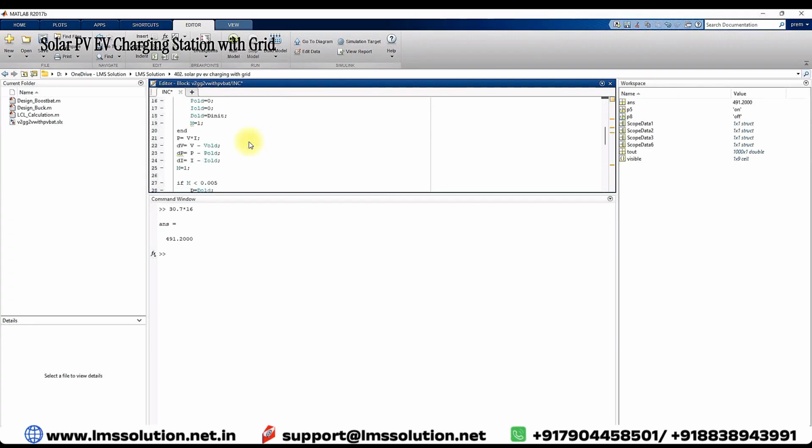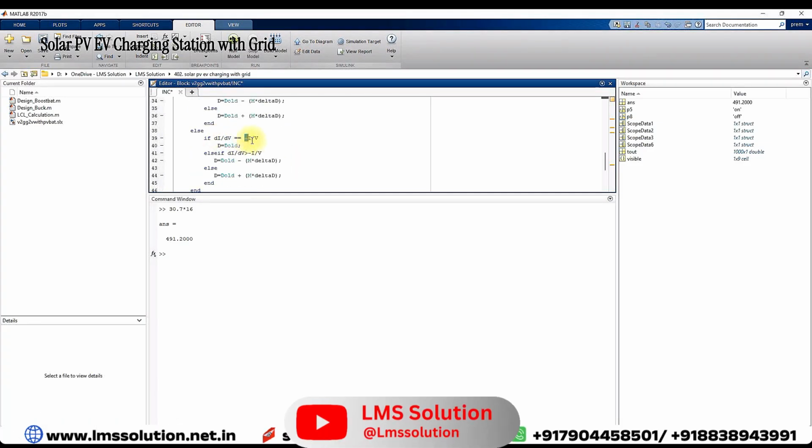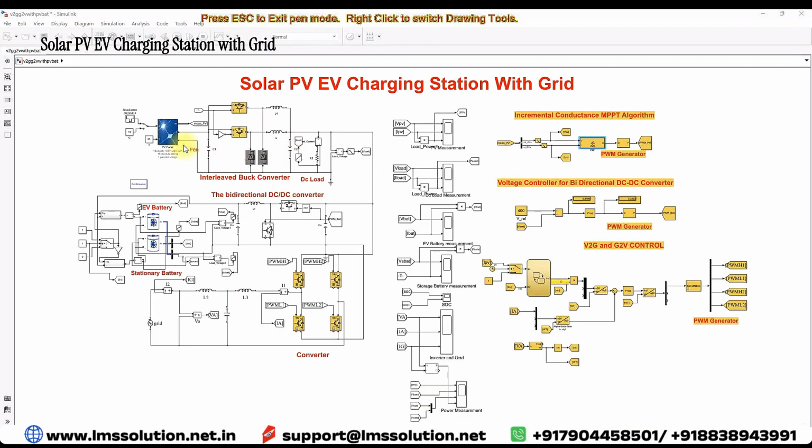Then you have to calculate the change in voltage, change in power, and change in current, and based upon the change in voltage and change in current, you have to increment or decrement the duty cycle. This keeps executing to find the duty cycle for the interleaved buck converter, to step down the voltage from 500 to 400 volts, as well as extract the maximum power from the PV.